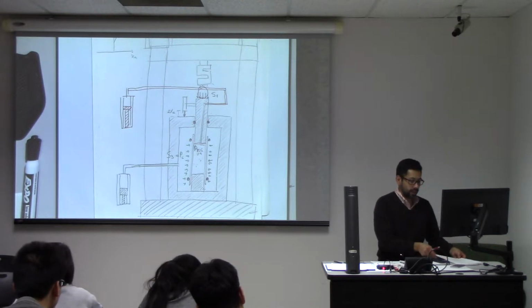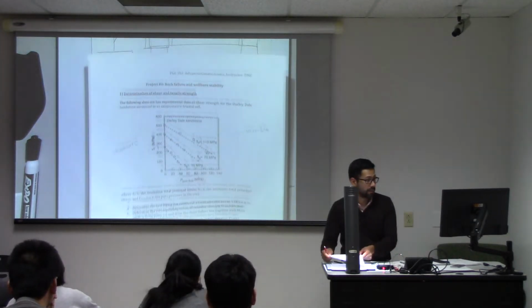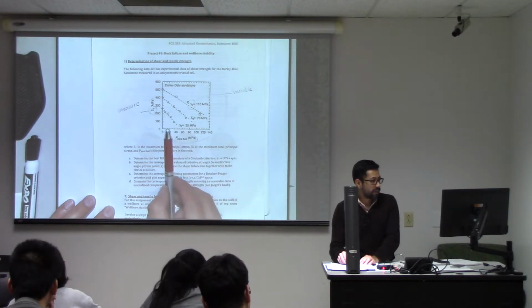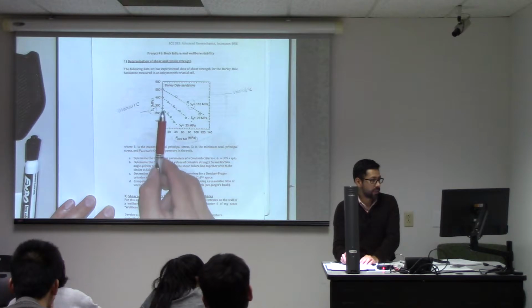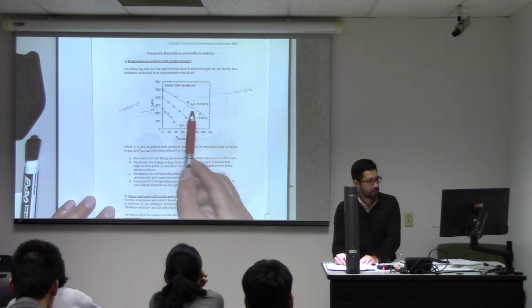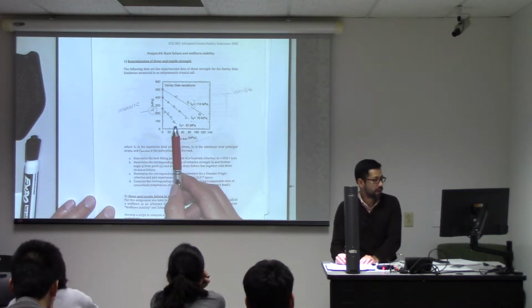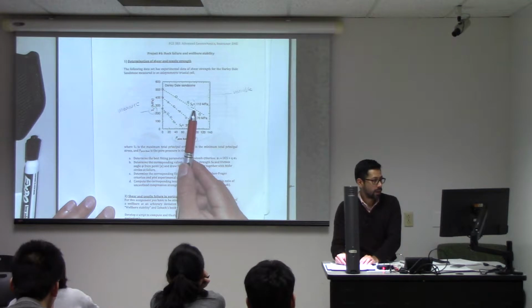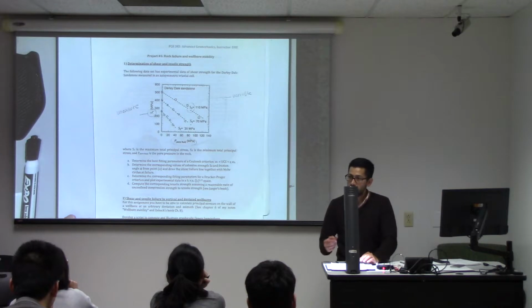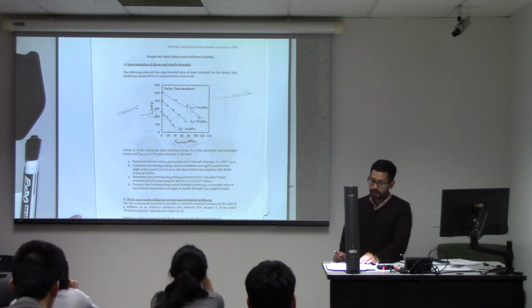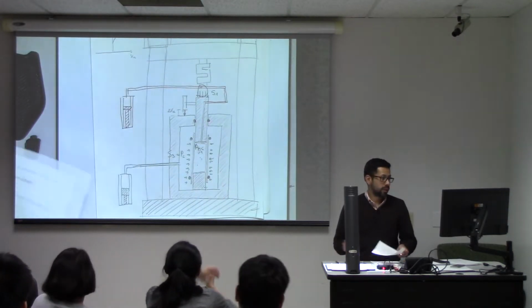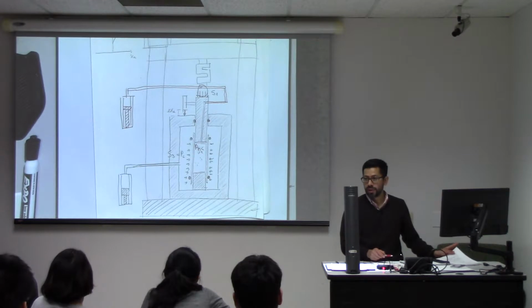And this is the data that you have here that you have to work with, in which you have different pore fluids, pressures. For example, here these are all values for 0. Different confining pressures going from 35 MPa to 110 MPa, and each of those are the readings of the maximum total stress. Notice that now we're using total stresses. In such a machine, like this one, you measure total stresses.